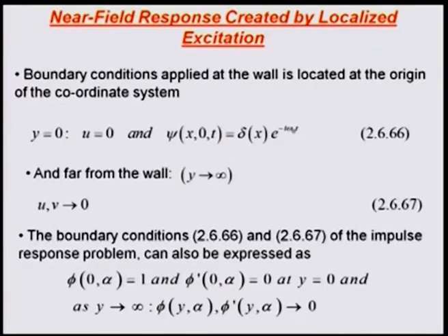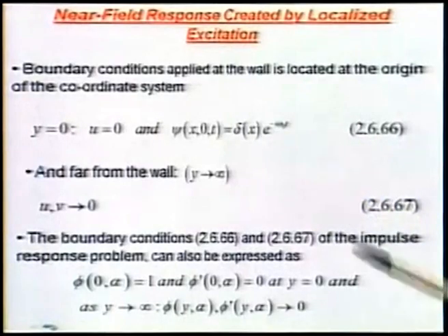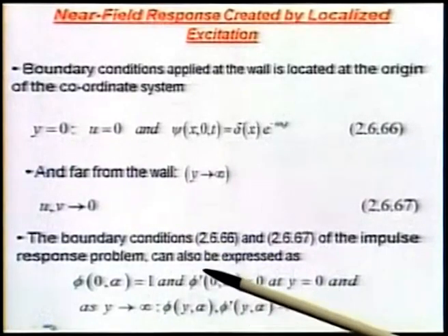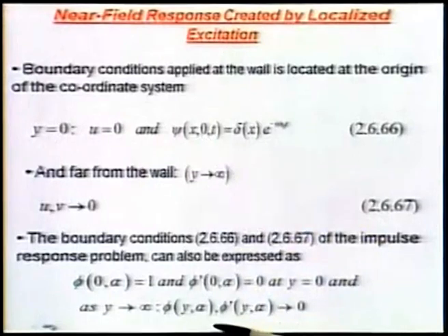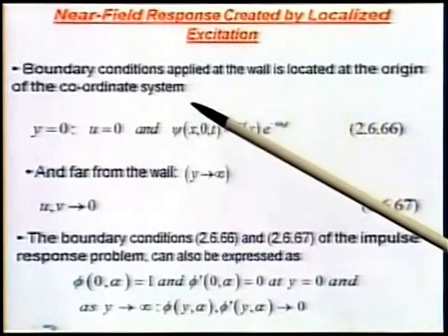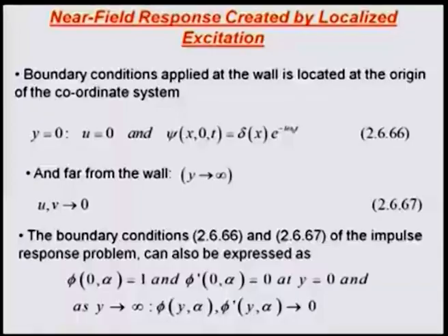Well, we are going to solve that equation subject to this set of boundary conditions, four boundary conditions required for the fourth order Orr-Sommerfeld equation, two at the wall and two at the far stream. In the spectral plane, in the alpha plane, these four conditions become this, and positioning of the exciter causes this phi of alpha to be equal to 1.